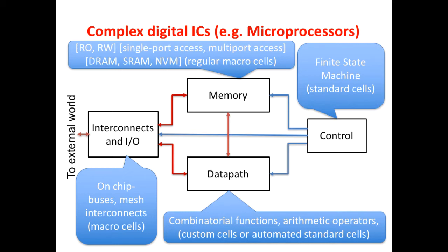And the main reason for that is that typically input-output components, since they have to communicate with the world outside the silicon chip, have to be able to have larger drive currents, because out of the chip everything is larger, we have larger capacitances, larger currents, and so the blocks must be able to cope with that type of circuit.